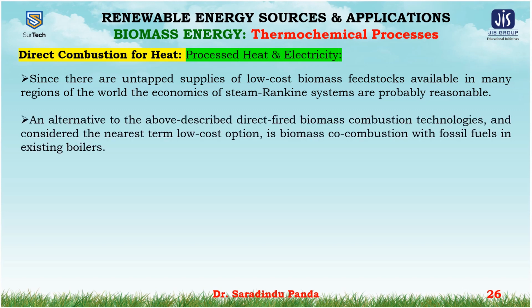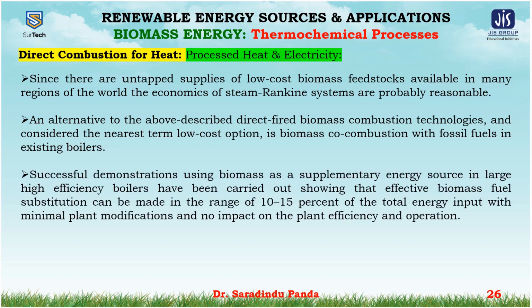An alternative to the above described direct fire biomass combustion technologies, and considered the nearest term low-cost option, is biomass co-combustion with fossil fuels in the existing boilers. Successful demonstrations using biomass as a supplementary energy source in large high-efficiency boilers have been carried out, showing that effective biomass fuel substitution can be made in the range of 10 to 15% of the total energy input with minimal plant modifications and no impact on the plant efficiency and operation.